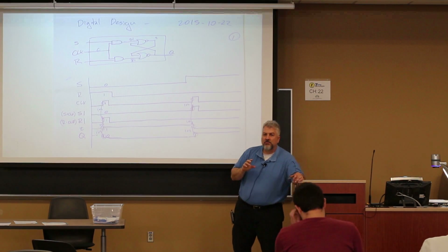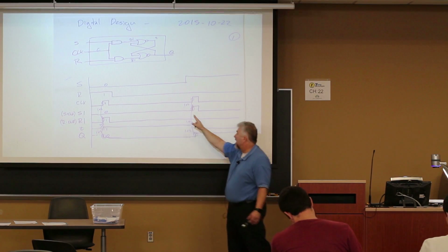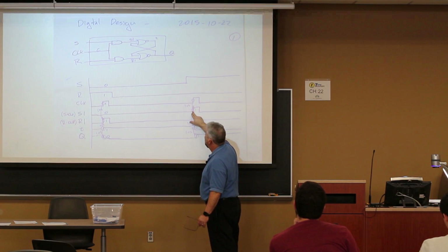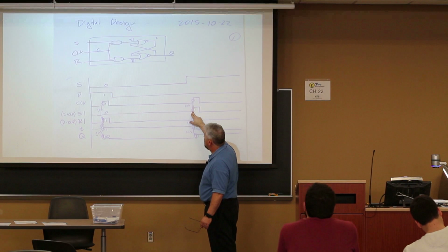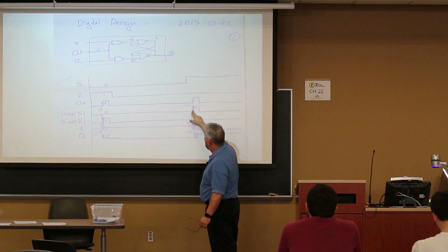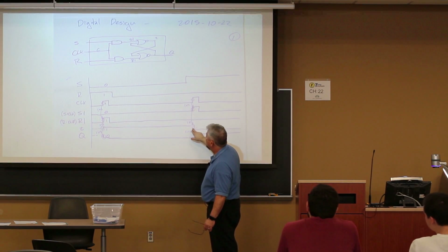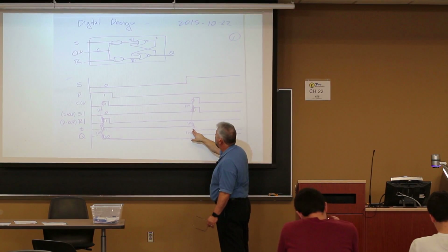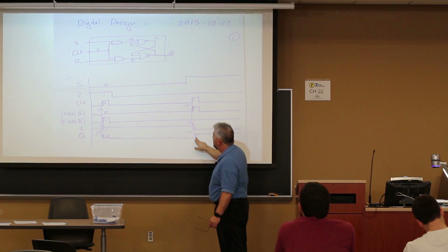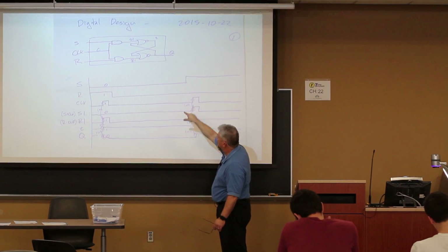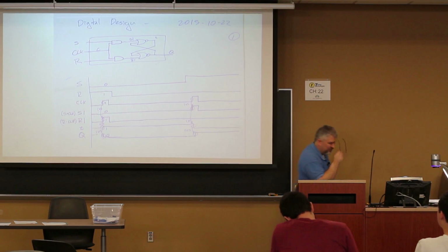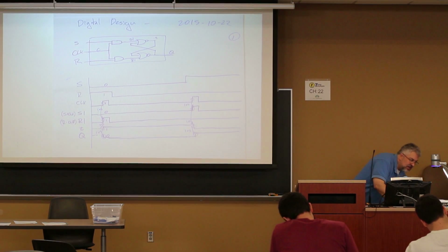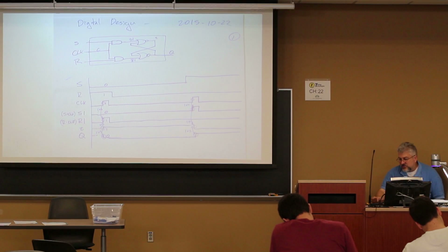And that's the whole concept of sequential circuits. So at the clock itself, then that AND gate, 1 nanosecond later through the gate, goes from a 0 to a 1. And then 1 nanosecond later, it's adjusting T. And then 1 nanosecond later, it's changing the output for the lower NOR gate for Q. And that's the whole objective of this hands-on exercise we just did.